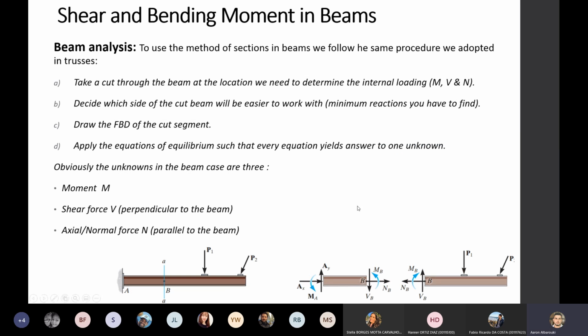Let's go back. Ignore this half here. Let's say we're going to take this half. I need to add a shear force here. How can we make it in the positive direction? If we add this force in a way trying to rotate this member, this half we're taking, clockwise. Look at it, this force is trying to rotate this member clockwise. That would be positive. All good?